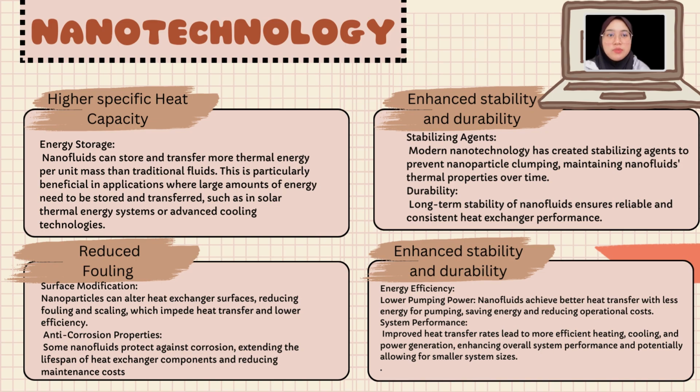The nanofluids can exhibit higher specific heat capacity compared to the base fluid, allowing them to store and transfer more thermal energy per unit mass. This is particularly beneficial in applications that require significant energy storage and transfer. The nanoparticles can modify the surface properties of heat exchanger materials, not only from an analytical perspective, but also as a driver of innovation across multiple technological domains. So some nanofluids possess anti-corrosive properties which protect the heat exchange surface and extend the operational life.